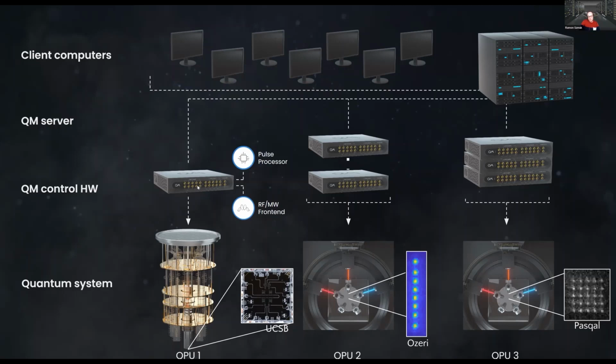So this is also very useful if you want to use some of the OPX channels to do, I don't know, spectroscopy or laser locking. Some customers want to do that to have the flexibility to change some locking parameters, for example. So you can do Pound-Drever-Hall with the OPX.